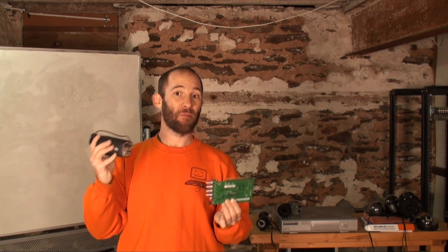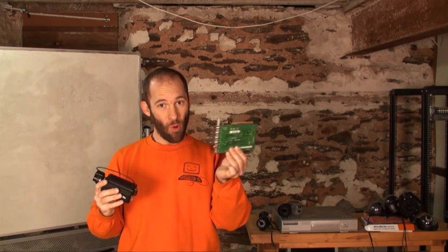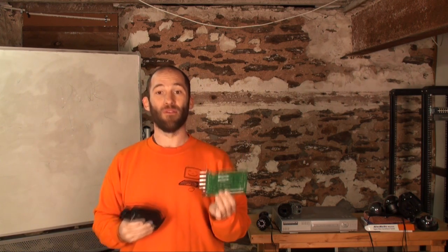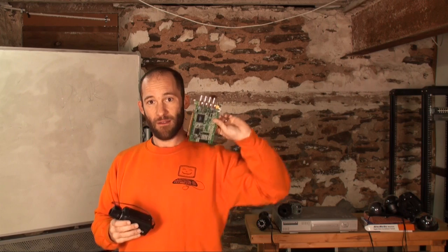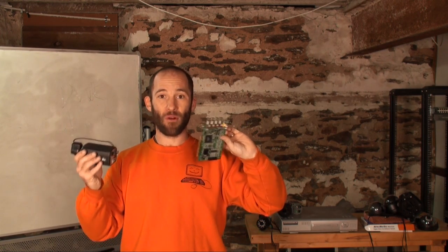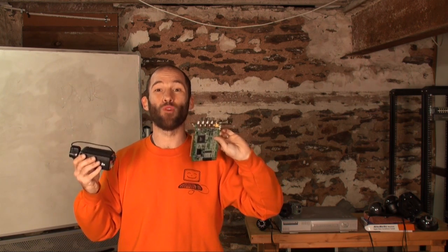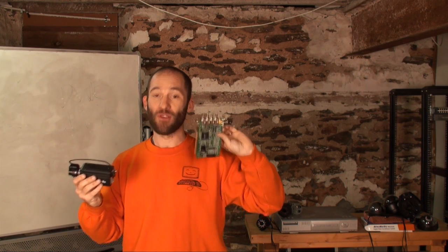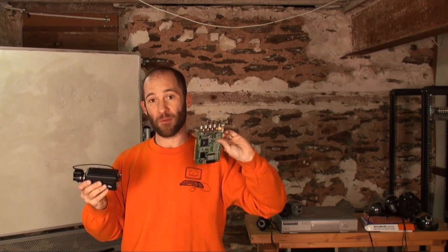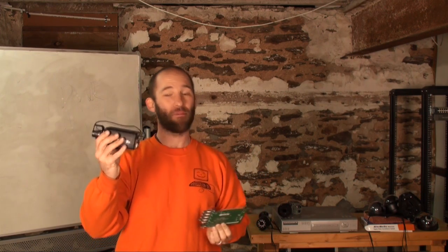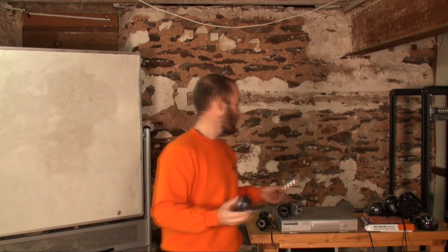If the channel says 30 frames per second, make sure the board can then do all those different channels. A four channel board with 4 cameras, in order to record real time, would have to be able to do 120 frames per second. If you see that the board only does 60 frames per second, that means 1 camera can be real time, and then you have to divide up the frame rate between everything else. So that is FPS, or frame rate per second.